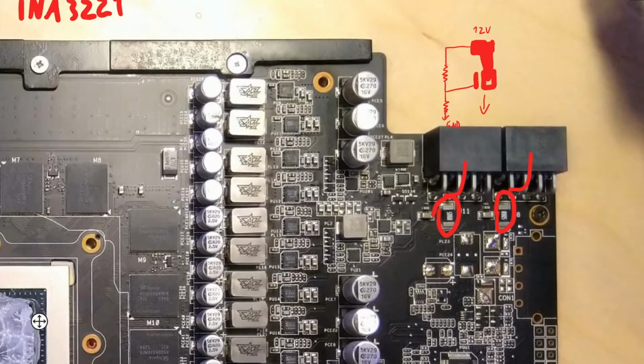So on the 20 series, this just doesn't work anymore for some reason. Likely because NVIDIA put some new power sensing circuitry on the card that is separate from these shunt resistors. And that's probably where the card still gets the power reading from. So it doesn't work anymore on the 20 series. And there's also a chance it doesn't work on 10 series cards, because some cards have a normalized power limit, as it's called by HW Info. And that normalized power limit does not get changed by doing this mod.